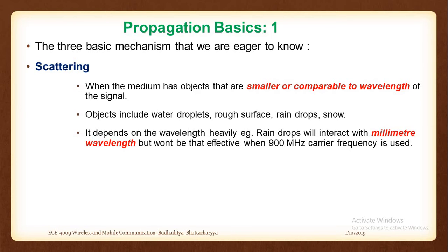It will reduce the transmitted power, hence the received power will not be sufficient enough. Now, as we all know, there needs to be sufficient received power at the receiver so that voice communication can take place. So based on that, you have to modify the transmitted power and take these losses into account. So these losses need to be modeled.